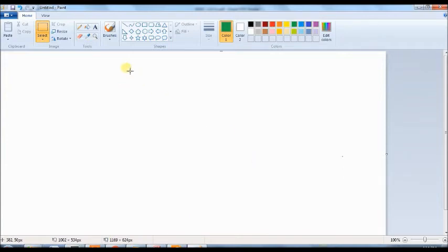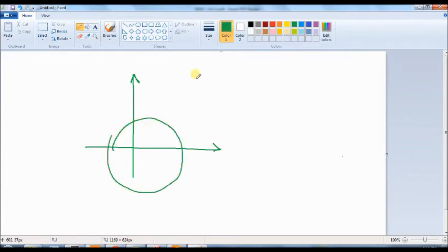So when you have one positive principal stress and one negative, the center of the circle is somewhere here. As I told you, there are another two circles here, and this is sigma A, this is sigma B, and the maximum shear stress is sigma A minus sigma B, divided by 2.